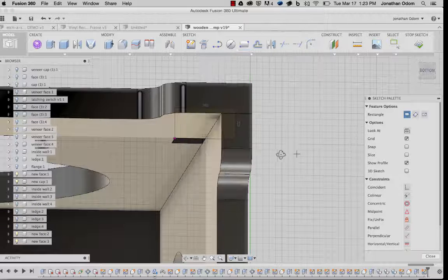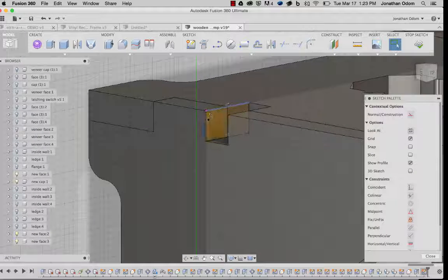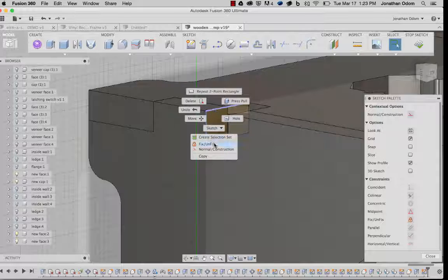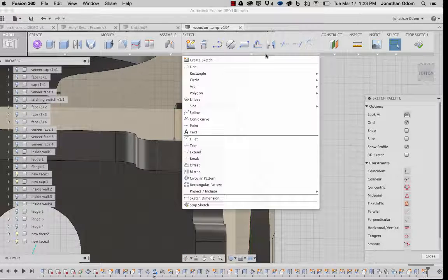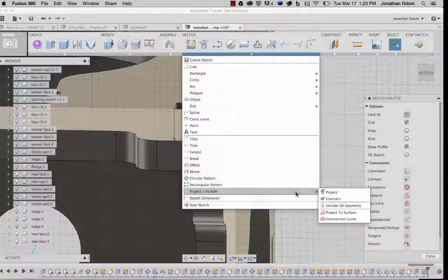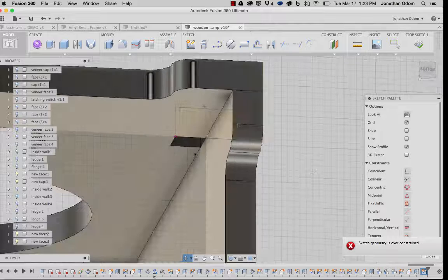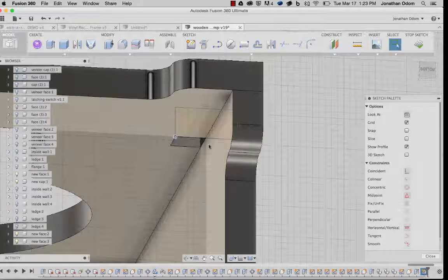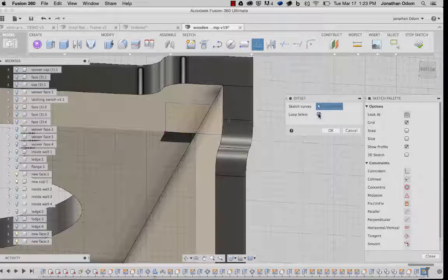I'm going to give this parameters. I want to fix both of these lines because I want those to be consistently on the outside. I'm going to make this dimension from here to here. I'm not saying it's over constrained, it's because of this point here. So I can get rid of that point. Actually, there's no need to, because if the thickness changes, this is going to go along for the ride. So what I'm going to do is keep this simple. Offset this by thick.